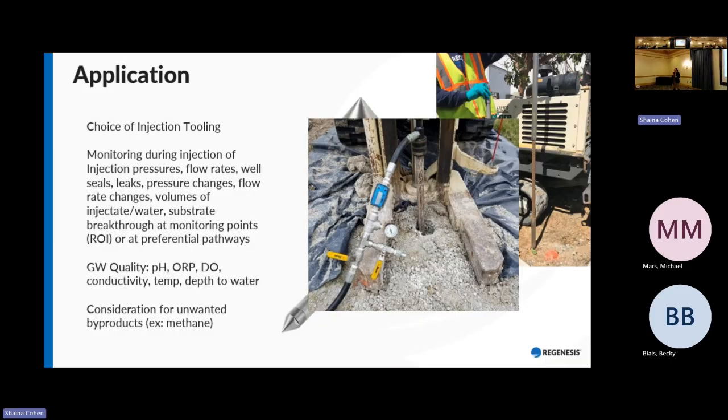And then lastly here, just a minor point that I felt like I had to address, though honestly it doesn't come up too often as a concern, is potential unwanted byproducts of these reactions, methane being the predominant one, but usually it's quite transient, and it honestly doesn't present itself too often. And believe me, I would be getting calls all the time if this was something that was really presenting itself as a concern on site after site. So it's just something to be aware of, particularly if these injections are happening below a building with a big concrete slab or something, right? Just something to be aware of.